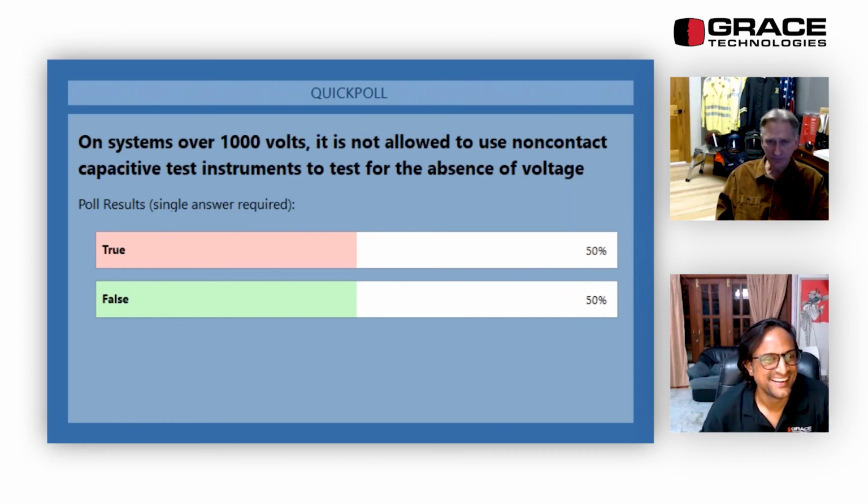But one of the things that comes up from this: I've consulted with a company before, and they've got an MCC bucket or a piece of switchgear that has a very high rating. Maybe it is 60 calories of incident energy.